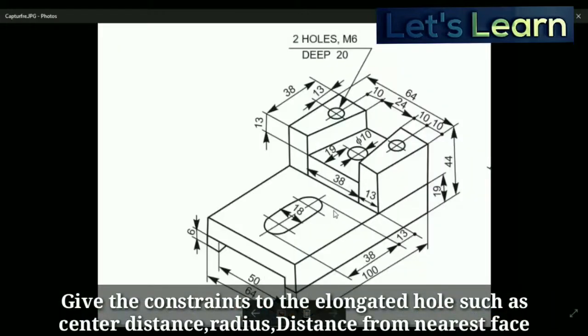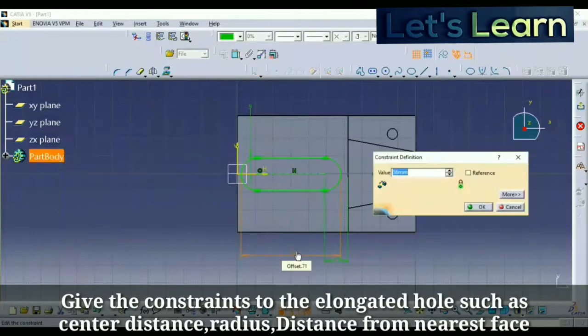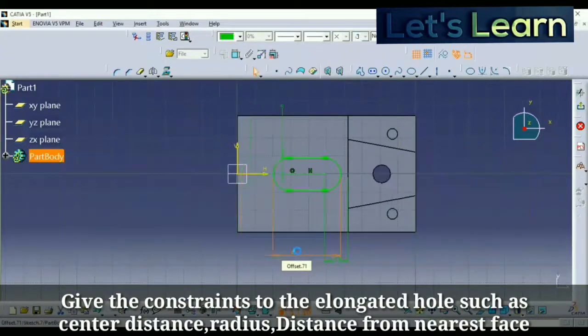Okay, I think there's one problem here. The hole is about 38 mm, so this is not proper. So just delete it, click on one circle then another, and then give the constraint. The whole length is 38.